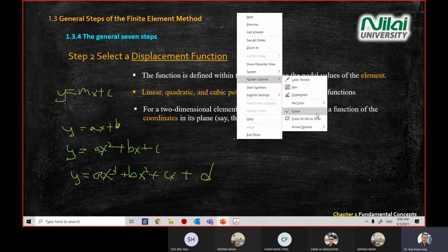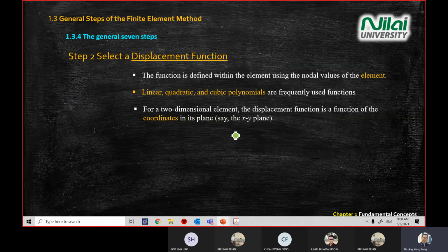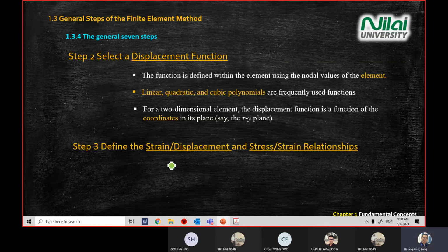The second step is about the equation. The third one, you need to recall what you learned: strain and displacement, stress and strain relationship. In this case, since this is your first class, I give you the formula recap. So deformation, du dx, all right, means the change of dimension along the x direction, du dx, and given by this epsilon x.